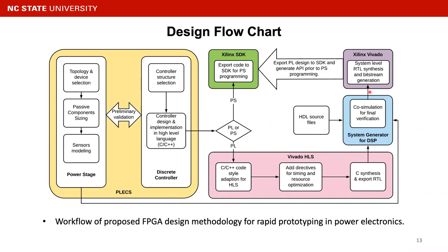After this final round of verification, we can export all our design into the Xilinx Vivado environment. In this software, we will run system-level RTL synthesis and bitstream generation. After the bitstream generation, this concludes the development for the PL side. Then once the PL design is finalized, we can export that to the SDK environment, generate the proper API drivers, and then we can start our PS design in the Xilinx SDK environment.